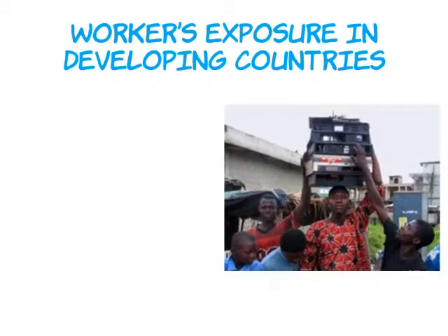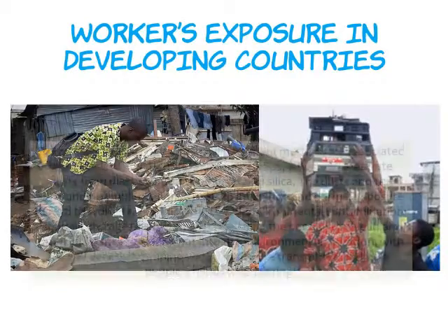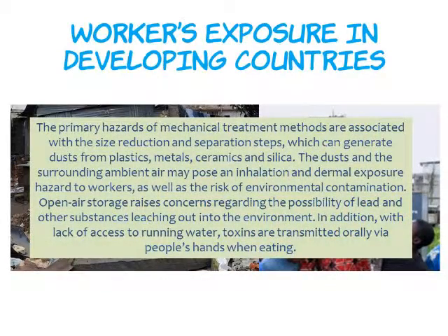Where formal facilities exist, measures can be taken to improve health and safety during exposure to most heavy metals and other chemicals. Such measures include provision of an enclosed and fitted work area with exhaust ventilation. When adequate ventilation is impossible to maintain, respirators should be carried and air should be sampled to determine substance concentrations.